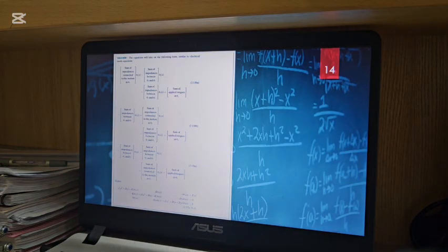We will have here the sum of impedances connected to the motion at theta 1, minus the sum of impedances between theta 1 and theta 2, minus the sum of impedances between theta 1 and theta 3, equal to the sum of applied torques at theta 1.